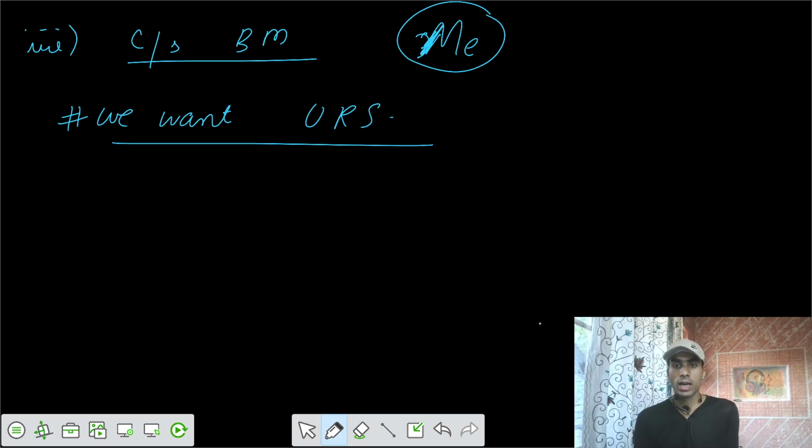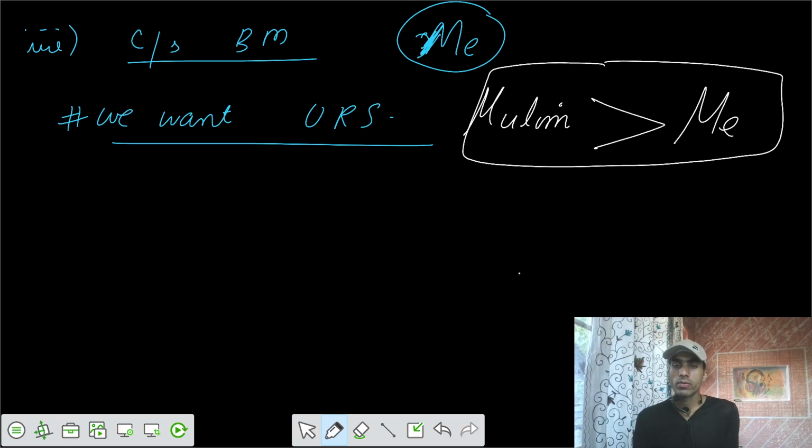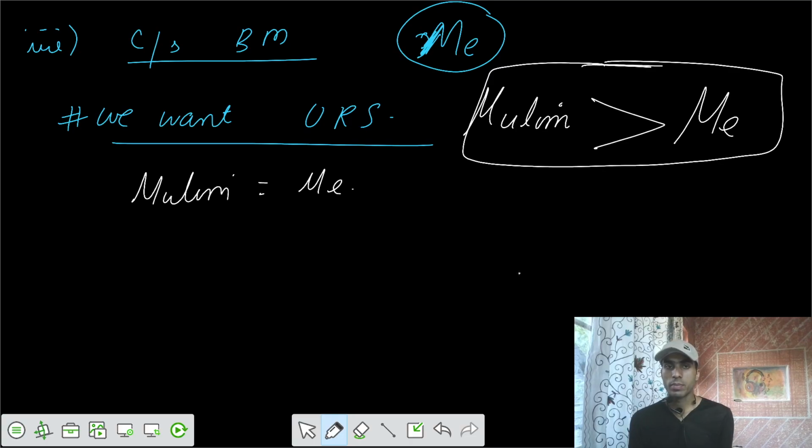So for that, the limiting condition is that our limiting moment should be greater than M external. If I talk about a balanced section, I would say the limiting moment should be equal to the external moment. But if I prefer an under reinforced section, this should be greater than.